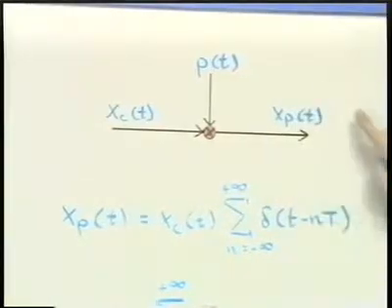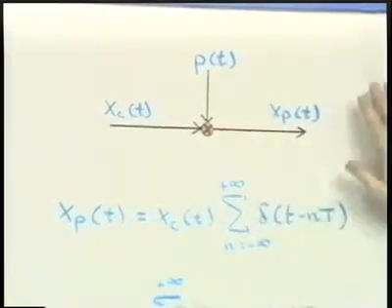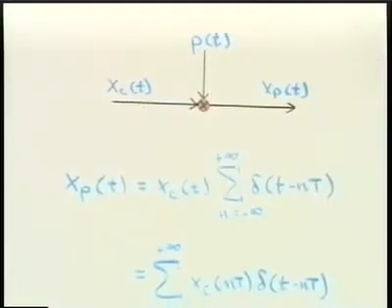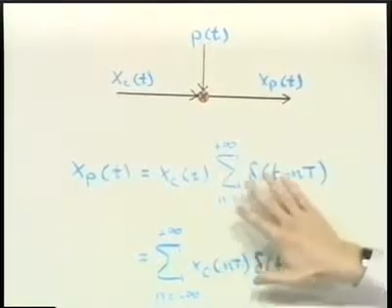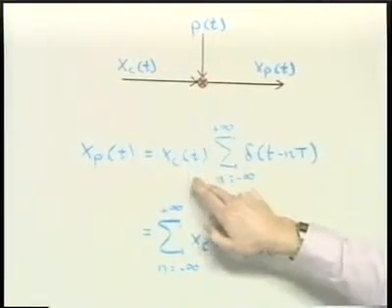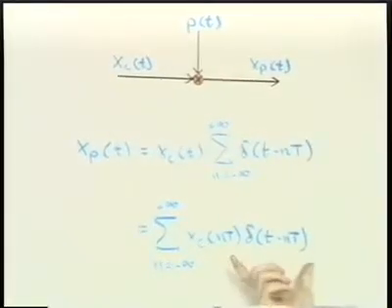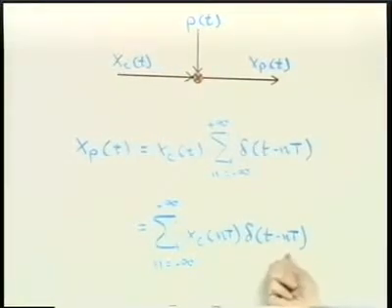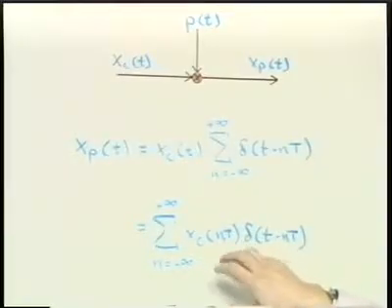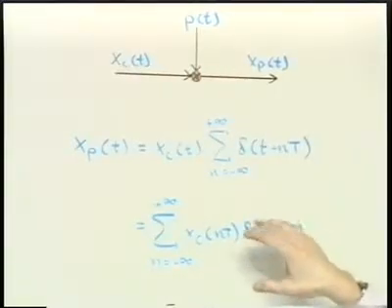And that gives us then another continuous time signal. We're still in the continuous time domain. It gives us another continuous time signal, which is an impulse train. And in fact, we've gone through this analysis previously. And what we have is this multiplication, or taking this term inside the summation and recognizing that the impulse train is simply an impulse train with areas of the impulses which are the samples of the continuous time function, we can then carry out the analysis in the frequency domain.